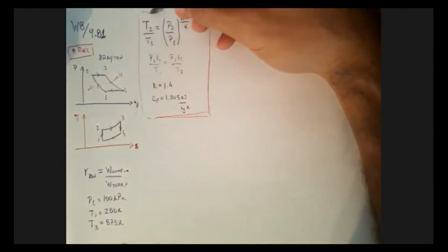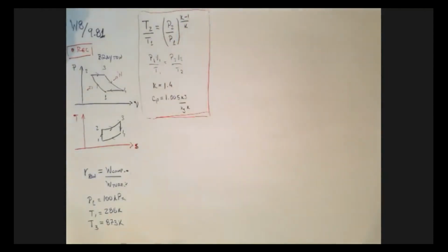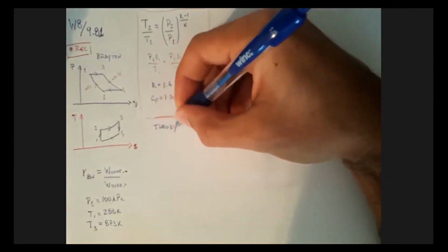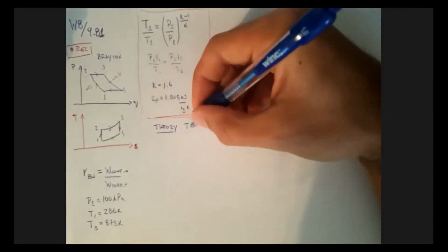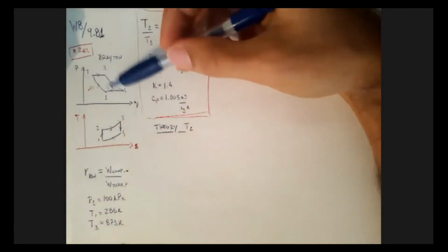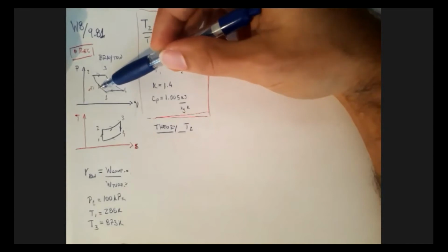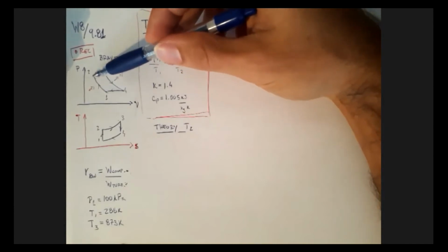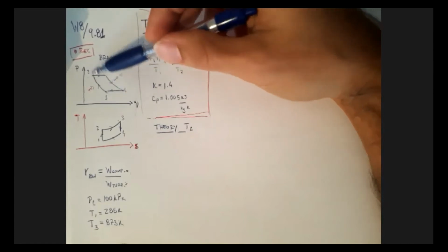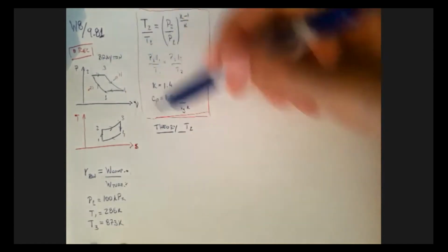The way I'm going to do it is to calculate the theoretical value for T2. When we go from 1 to 2, if my compressor does reversible work, I'm going to end up at a certain temperature. But if my compressor has irreversibilities, it's going to end up at a higher temperature. And we want it to stop at the minimum temperature possible, right?